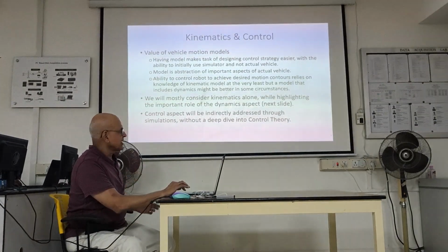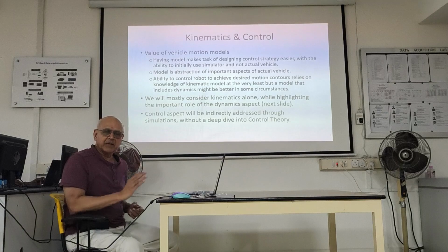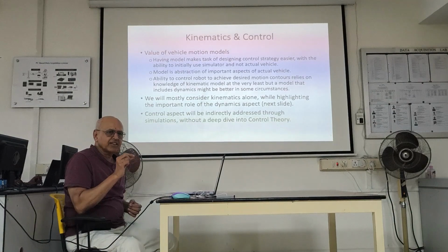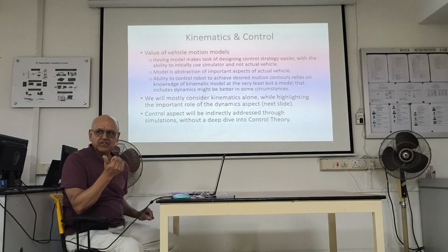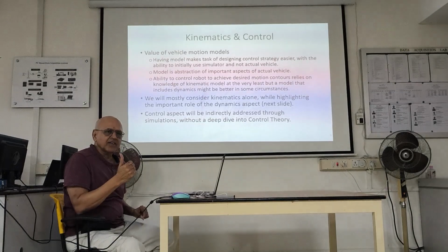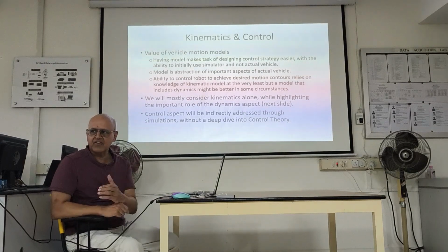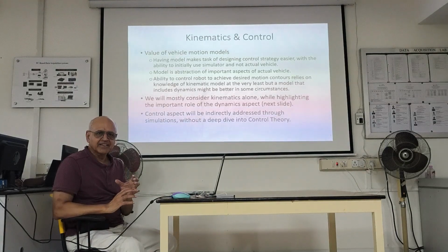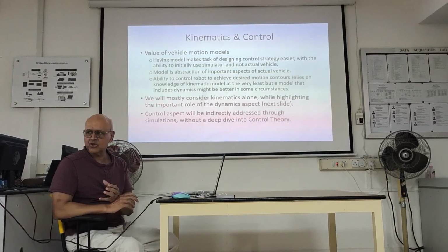So that's what we're going to talk about here, primarily the kinematic model, but I'm also going to tell you why dynamics is important. So dynamics is very important. It becomes less important in certain situations. It's never unimportant. If it's important and nobody pays attention to it, you know what the reason is? Convenience. Because of convenience, they say ignore it. But eventually it's there, you can't ignore it, right? In some situations, you can get away with a kinematic model. And those are when you're moving very slowly, or you have such powerful motors that the dynamic effect is not going to be really showing up.